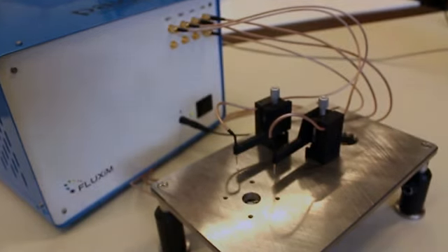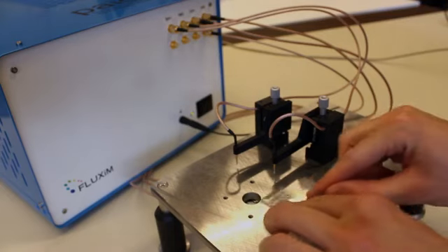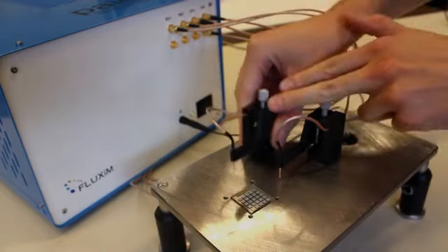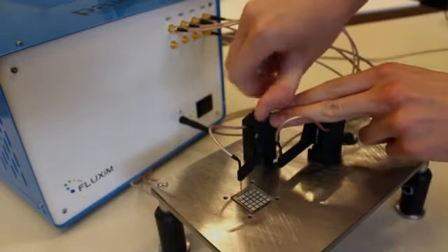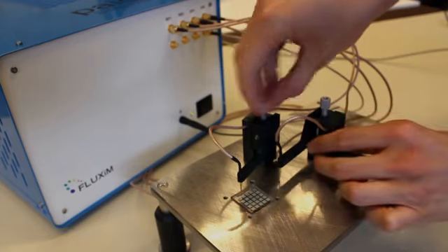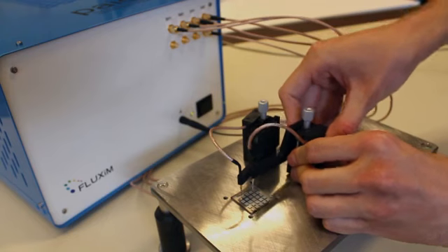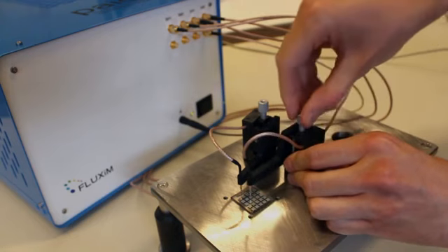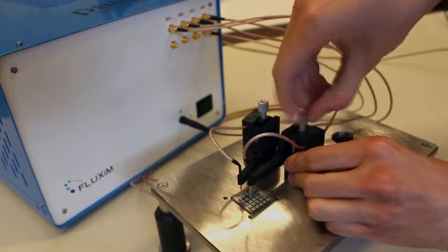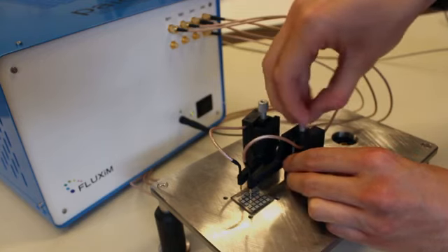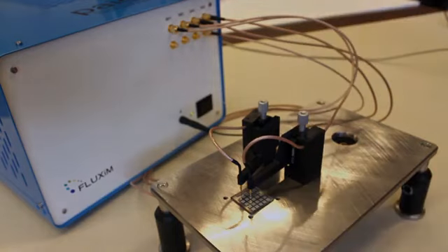Here you see the measurement table of Paios with the LED that is here below. And we now connect a test solar cell to make some test measurements. This solar cell is a microcrystalline silicon solar cell, and you see the surface is quite small, it's 9 square millimeter. We developed these magnetic contacting probes to have a flexible contact and to have a contact that is well suited for transient measurements. A good contact is the key for a good transient measurement.